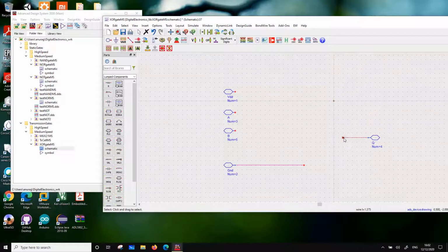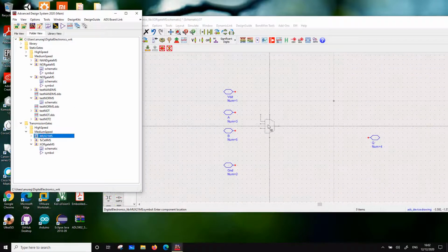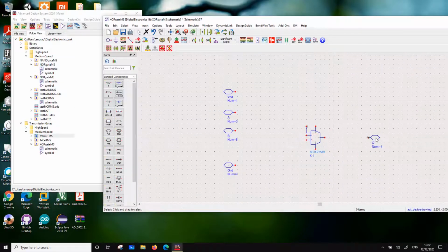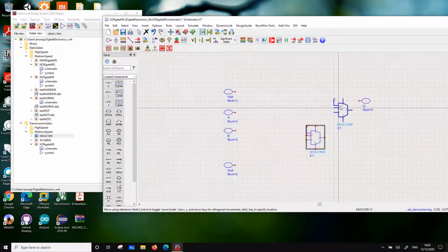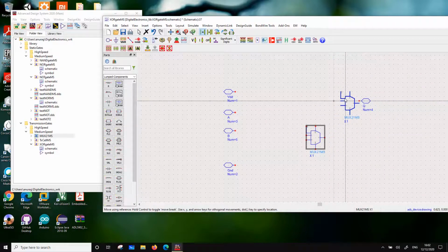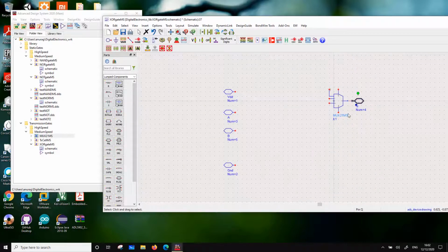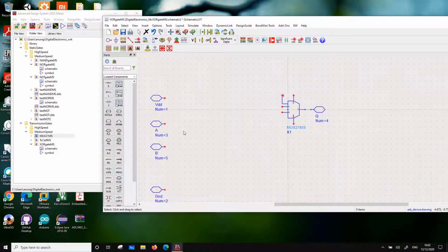Okay, what I do is I just introduce a mux here to the output. So there is a mux to the output. Okay, and one of the inputs is going to be the select line, the other input is going to be VDD and ground.